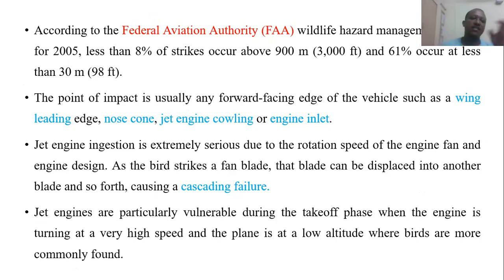Jet engine ingestion is extremely serious due to the rotation speed of the engine fan and the engine design. As the bird strikes the fan blade, that blade can displace into another blade, which locks another blade and can cause immediate destruction of the blades.